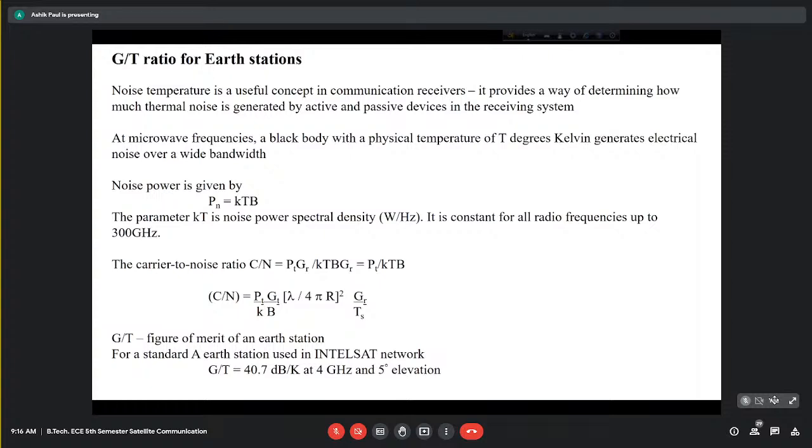so that whatever signal along with a large amount of noise is coming, we will accept that. And then, depending on the tuning frequency, we will select the bandwidth around that center frequency and gradually remove the out of band noise components.